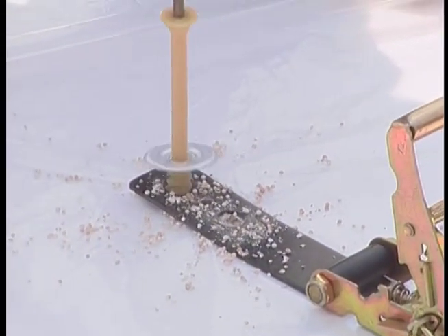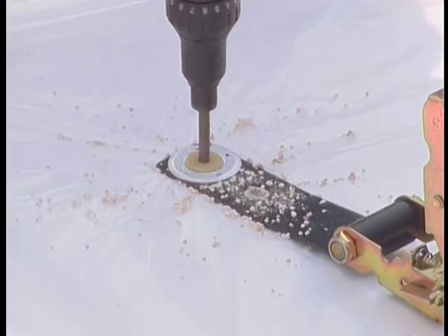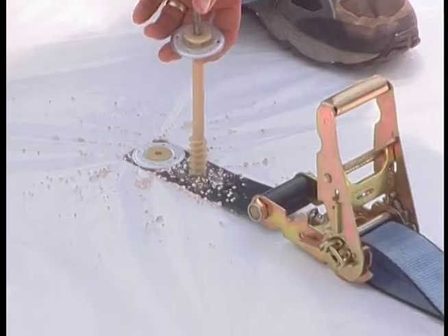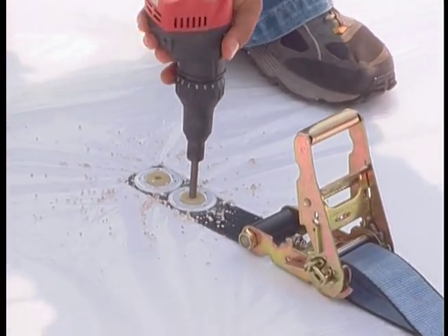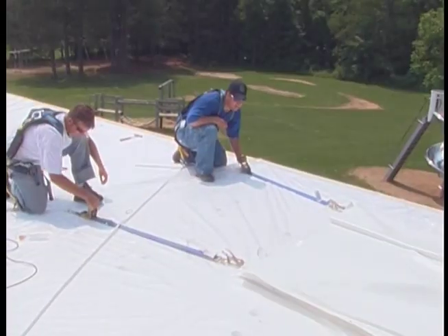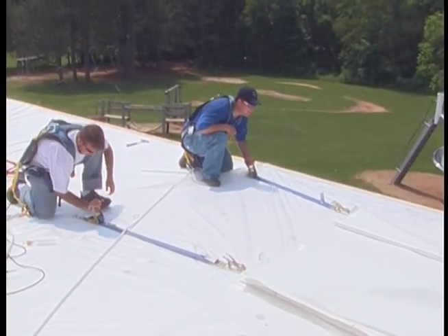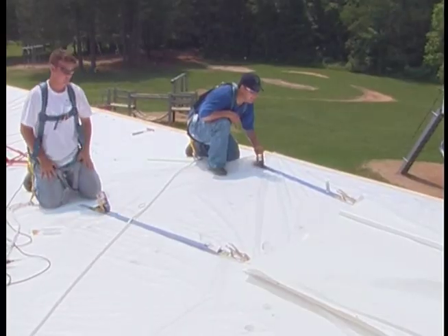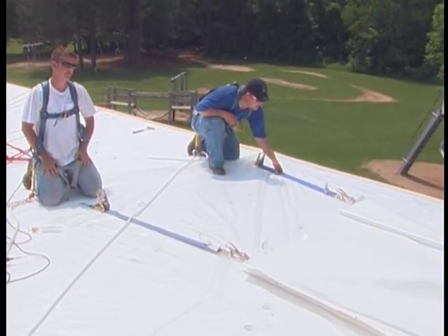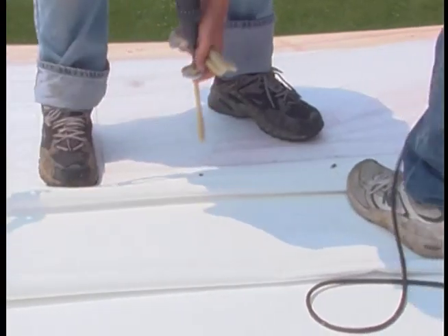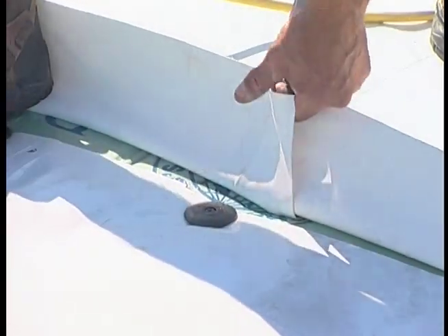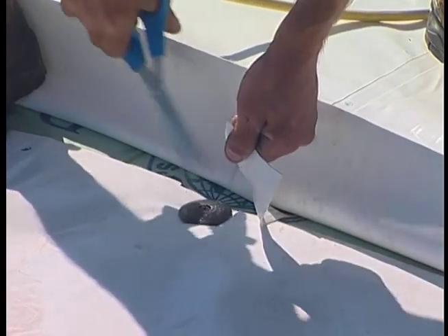Now fasten the ratchet straps through the existing roof system to the deck. Apply the 4-to-1 rule, which is, for every 4 feet away from the deck sheet, move the ratchets out 1 foot. Attach the vice grips to the factory welds and tighten the ratchet straps until the fastening tabs are taut and lying flat. After the fastening tab is positioned on the chalk line, go back and complete the fastening according to Duro-Last specification.